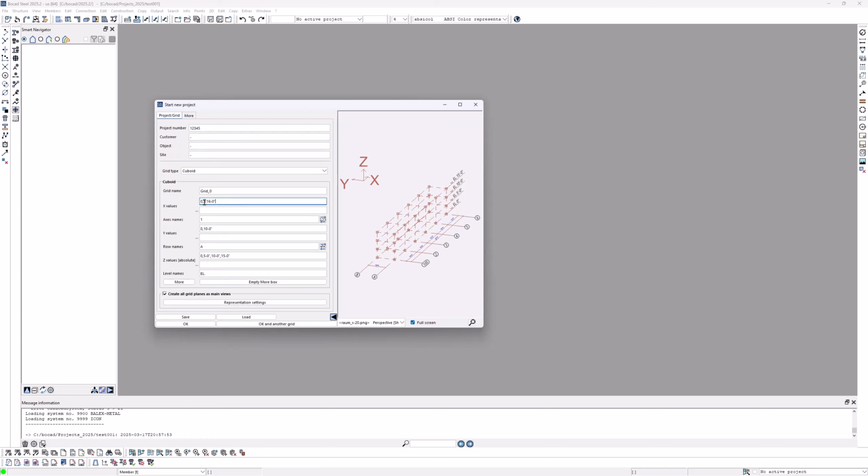The grid we are going to start with, we can start with various shapes of grids, and we can give our grid a name as well as defining the X values. So if I say we have 2 feet, 10 feet, 2.5 feet, enter to refresh the values, we will see a little update of indeed 2 feet, 10 feet, and 2.5 feet.